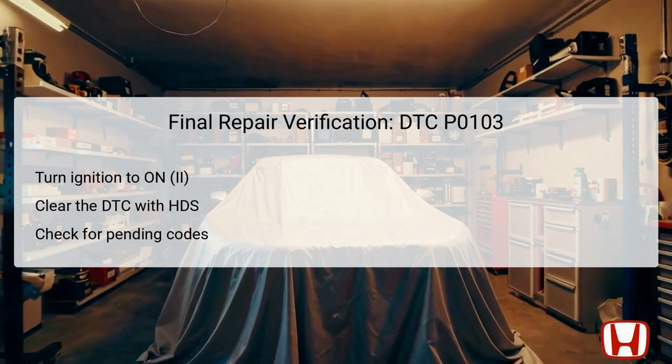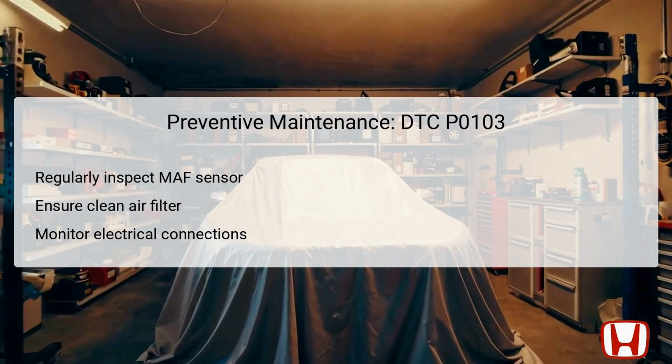After clearing the codes, check to see if DTC P0103 has reappeared as either a pending or confirmed code. If the code does return, it indicates the repair may not have resolved the underlying issue, warranting further inspection. However, if no codes appear, this suggests a successful resolution of the problem.